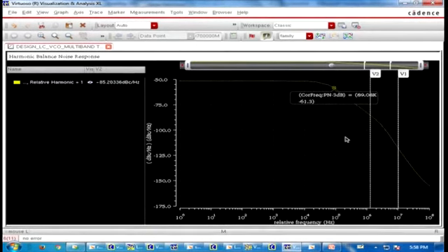Yeah, it is already published. Minus 122 is published, measured, everything. This is the new thing, 65 nanometer, and that I have done in 130 nanometer. That is for wireless communication, and this is not for wireless communication. This is for 2.4. This VCO will go into a PLL. Basically, it will go into a frequency synthesizer to serialize the data.